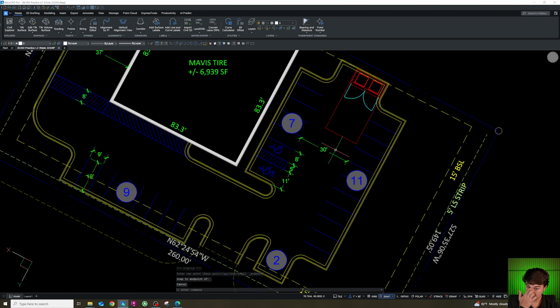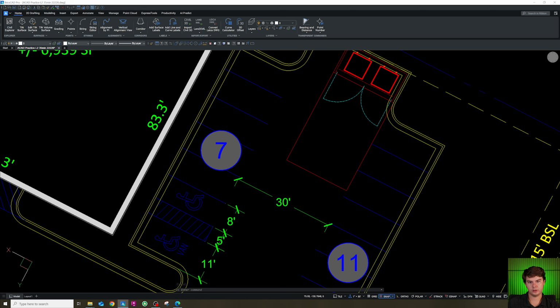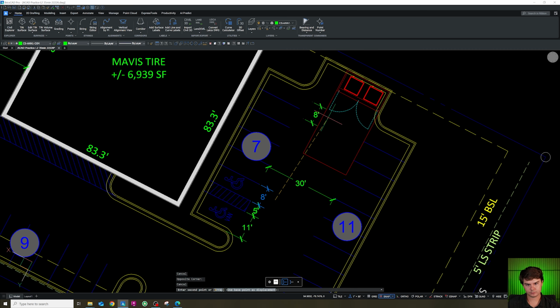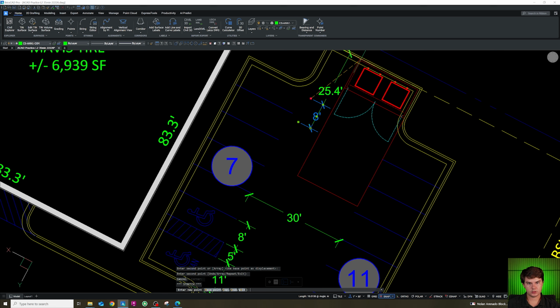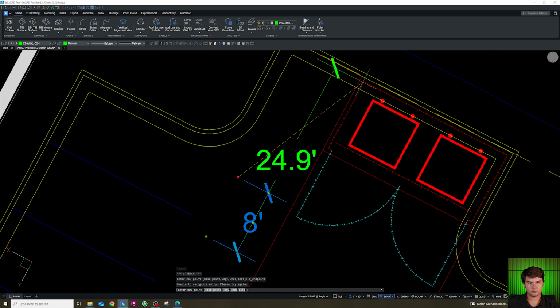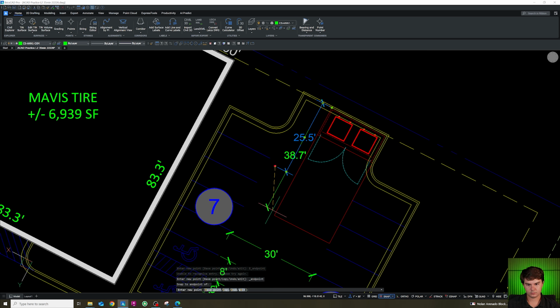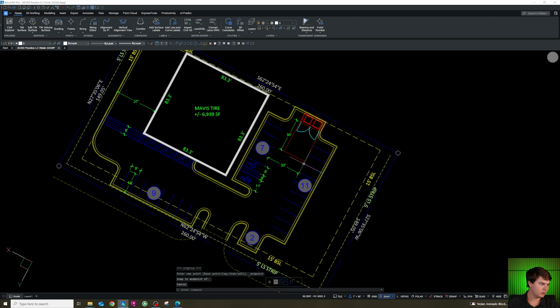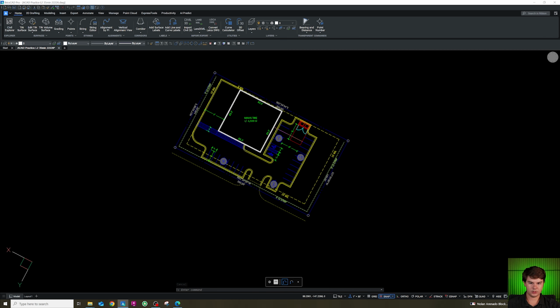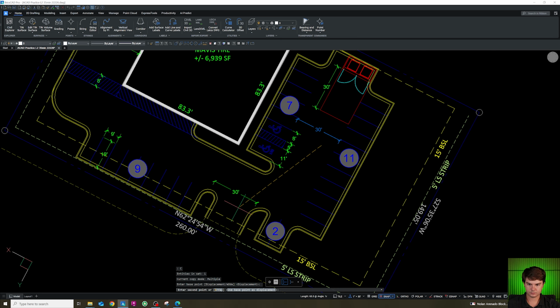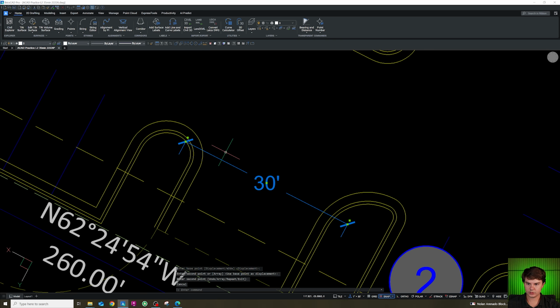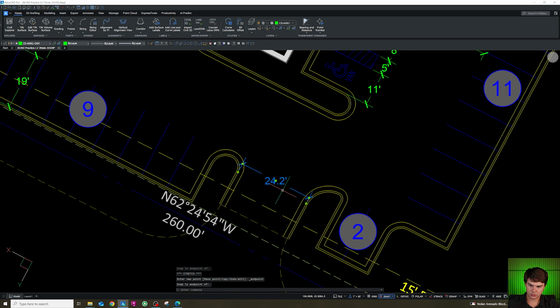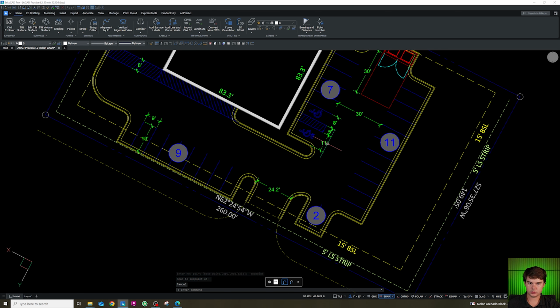Feet. We have to measure our area for our dump truck to come in. Measure that. And our drive aisle. Existing drive aisle. Always measure from this middle curb line, 24.2 and 27 here.